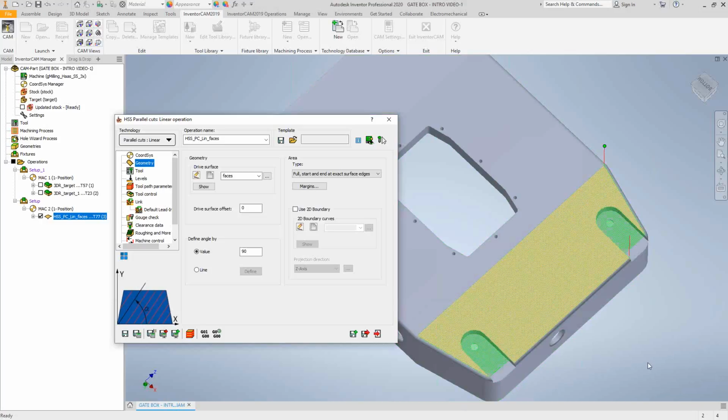This could be the case where maybe I haven't machined those slots yet, so I still want it to feed across there so it finishes that surface so there's no real burrs or any kind of discontinuity between the edges there. So it's just a good way to account for the surface. There is a training video on the YouTube channel where I show you how to cap that surface if you really want to completely machine that surface without worrying about the slot. Now let's take a look at the other option available, constant Z.